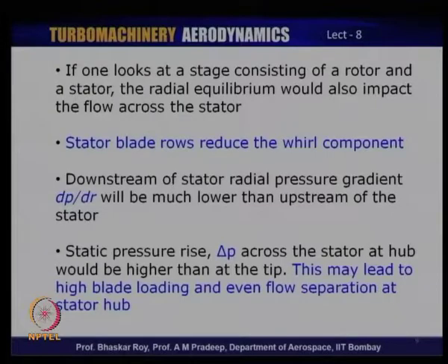Now, increased blade loading, increased static pressure ratio essentially means that the blade is aerodynamically loaded more. You are trying to get more out of it aerodynamically, and that is blade loading. Now, if you are trying to achieve a higher static pressure gradient, remember this is an adverse pressure gradient. So, pressure is increasing from front to the rear of the blade, and this creates a situation that the flow gets loaded, the blade is loaded and the flow is now on the brink of separation.